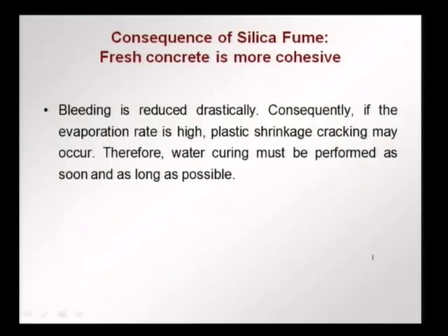However, this bleeding helps when there is very high evaporation when the concrete is still fresh. If this bleeding is not there, then plastic shrinkage cracking can occur. That means water curing must be performed as soon as possible and as long as possible. So, bleeding is not something that we would like to encourage, but understanding that silica fume concrete is going to have less bleeding, we should start water curing as early as possible, prevent evaporation so that plastic shrinkage cracking does not occur.